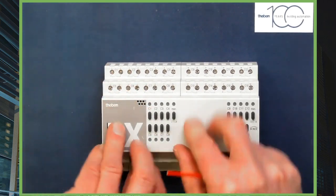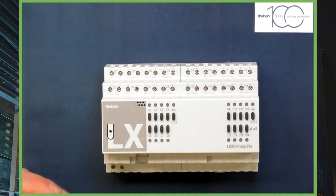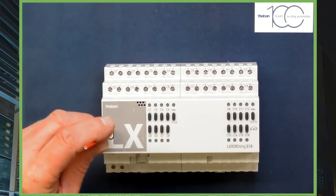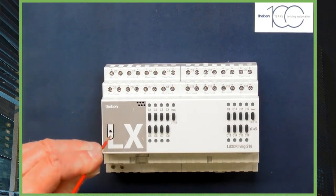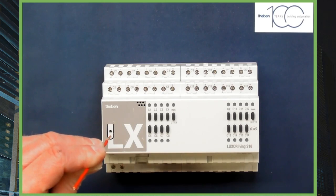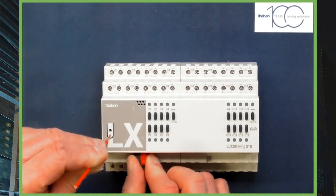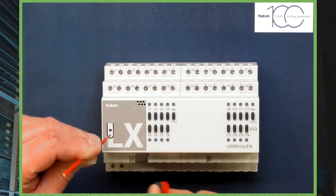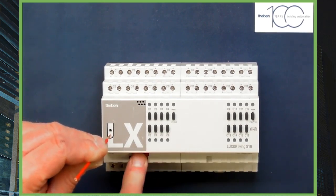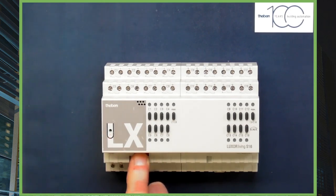If you disconnect the device from the bus, press the programming button, and then connect the bus cable again to the device, put it in here, and then after a while release the programming button.